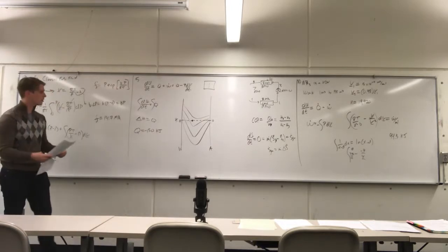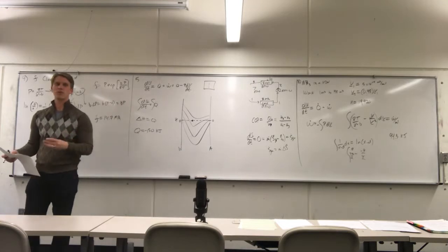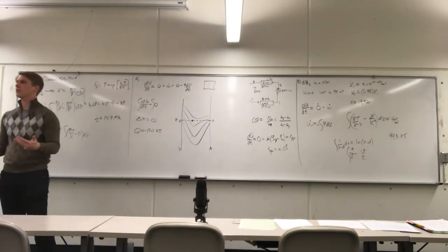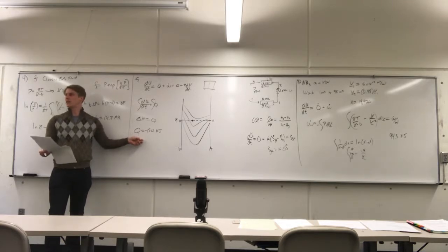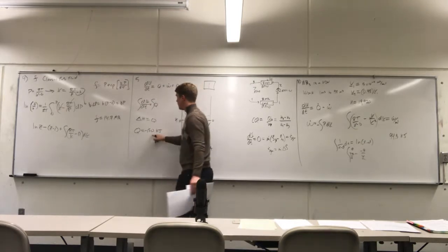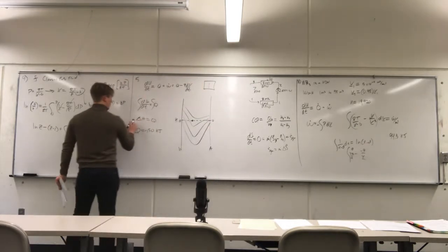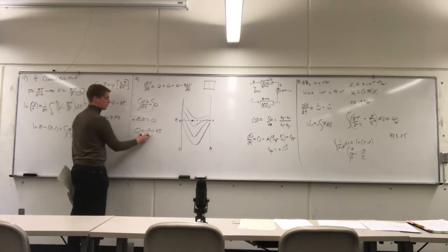So I was a little bit too nice on this problem. I should have made it so that it wasn't 1 kilogram of total mixture. If I made it so it was 4.8 kilograms of the total mixture, then you would have to actually be looking up how does that affect the change in the molar enthalpy, right? So in this case here, since all the math worked out quite nicely, the mass times the specific enthalpy change is equal to the Q out.